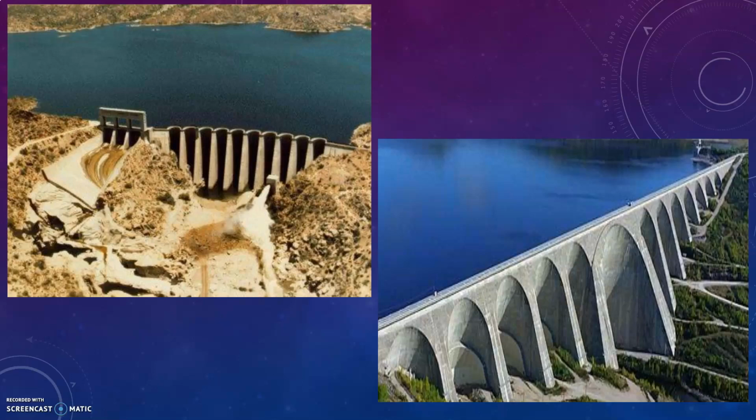The water load acts normal to the inclined deck, hence the vertical component of the water load stabilizes the dam against both overturning and sliding, and the buttress dam possesses a factor of safety much greater than that obtained in a gravity dam. In the case of gravity dam, the height of the dam can rise only by the provision of crest shutter at overflow section.